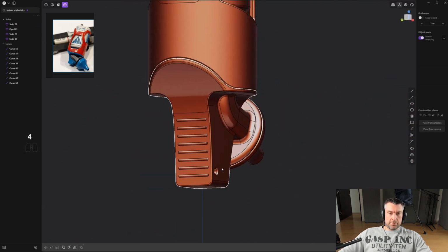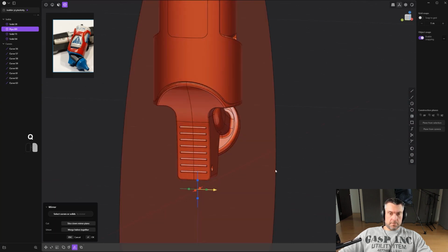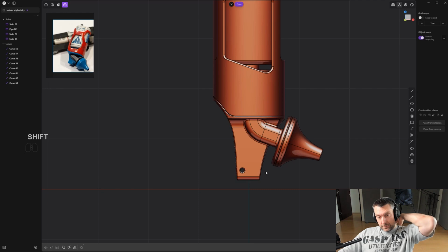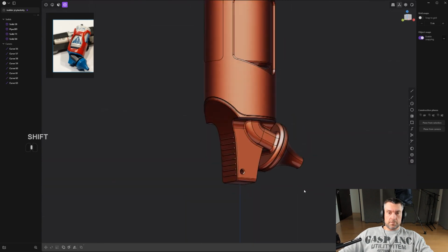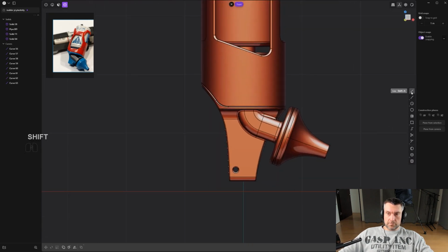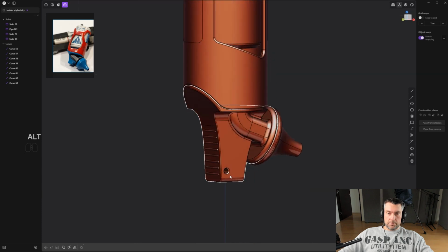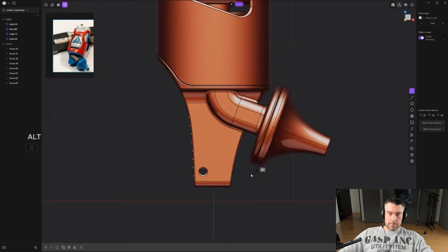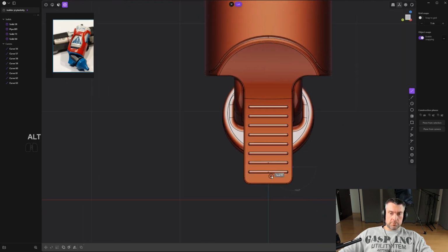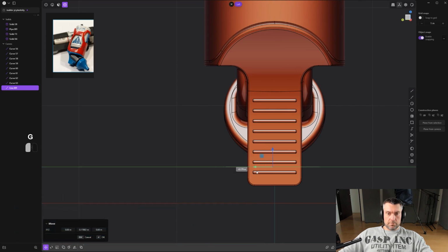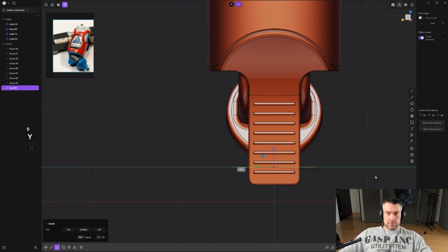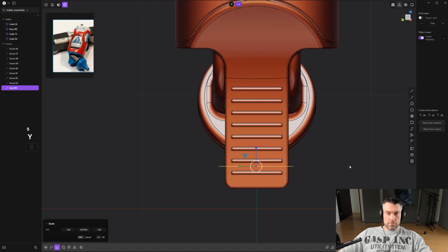So in fact we could run like a, what you call them, like a clip that, you know, kind of dangles down, and you can hold it or attach it to something. So let's run an edge here through the middle. So let's click here, go to side view and run this through. So let's just grab some flat edge, there we go, and move it in here. Then let's just scale this on y-axis a little bit more. Cool.